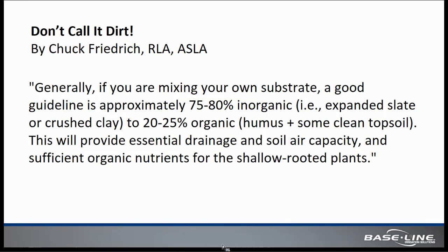Chuck Friedrich provided some good general guidelines in an article he published called "Don't Call It Dirt," where we want to have about 75 to 80% of the soil media inorganic and 20 to 25% of the soil media actually organic, that would provide good drainage, soil air capacity, and organic nutrient for the plant material in that application.